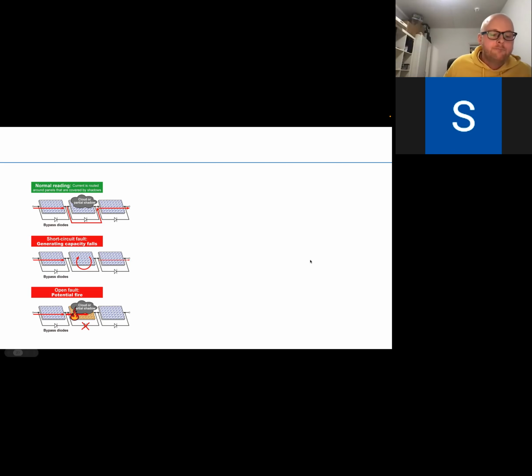Therefore, you would actually dissipate extra power in that shaded array rather than extracting power from it. So by not having this diode and pulling a high current, you're actually transferring some of the power of the non-shaded arrays to the shaded array, and therefore it might get super hot. And in this picture it even catches fire.